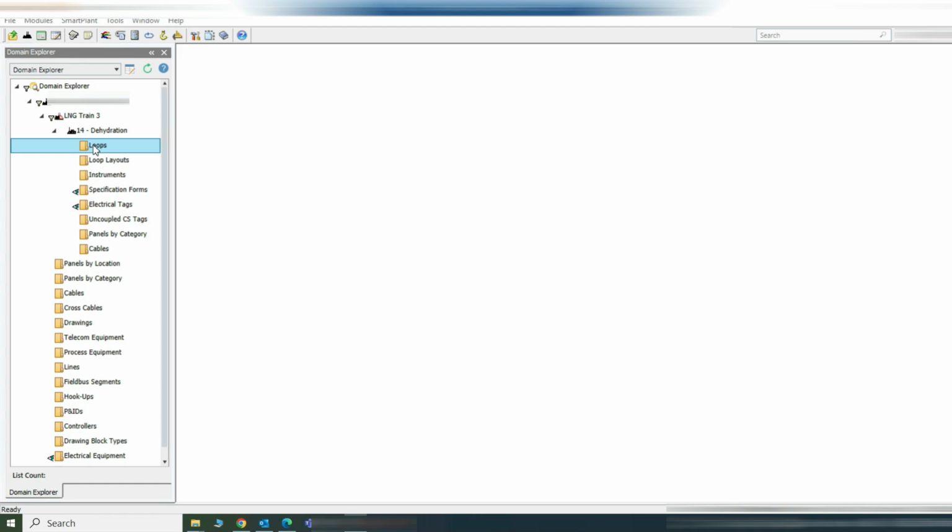The SPI admin will install that software once SPI is installed in your system or in your cloud. That Enhanced Smart Loop is dedicated to loop generation and loop corrections. Whenever you generate a loop drawing, the loops will be redirected to that Enhanced Smart Loop software.